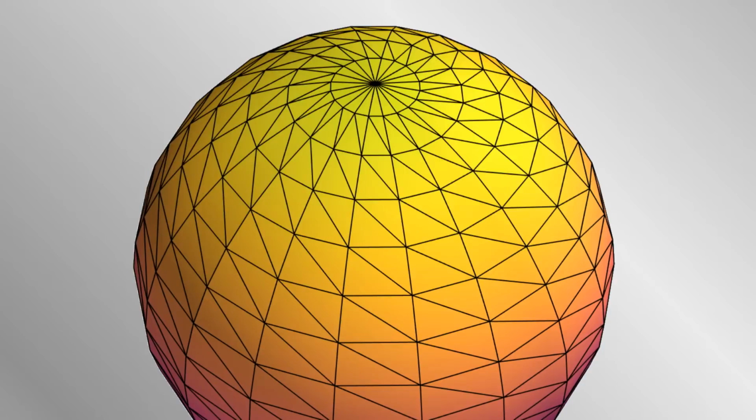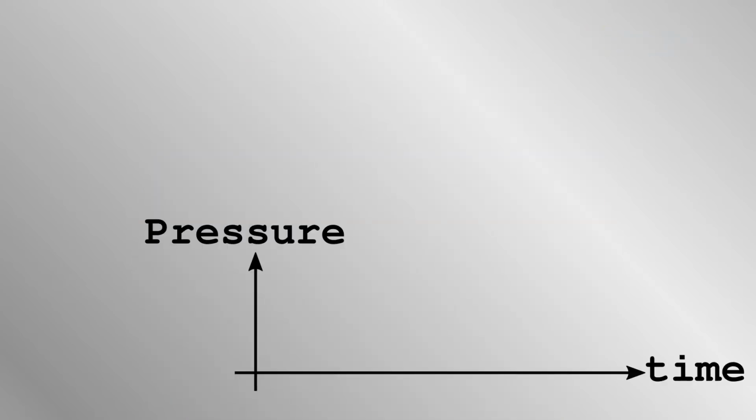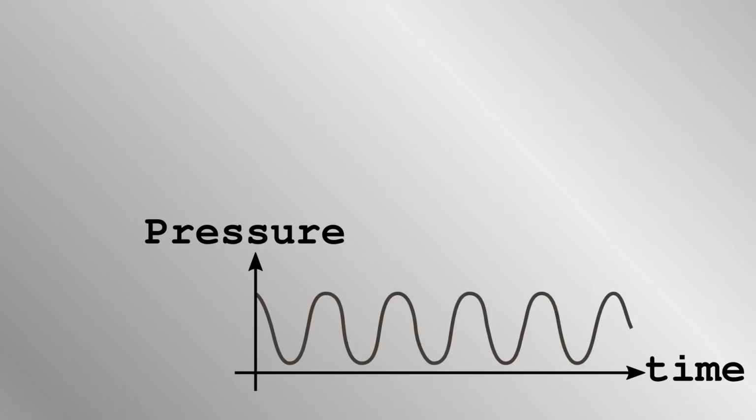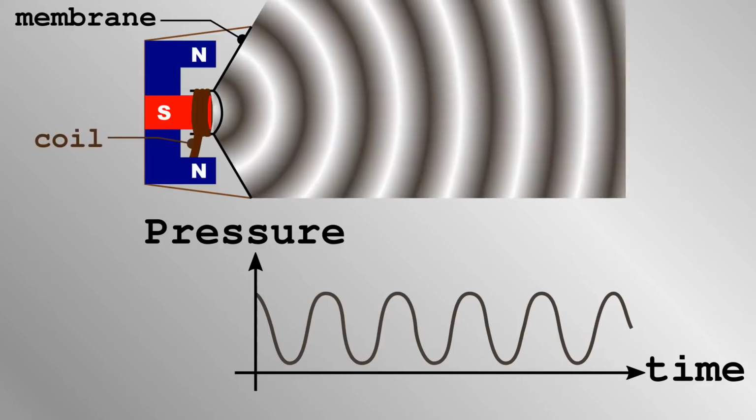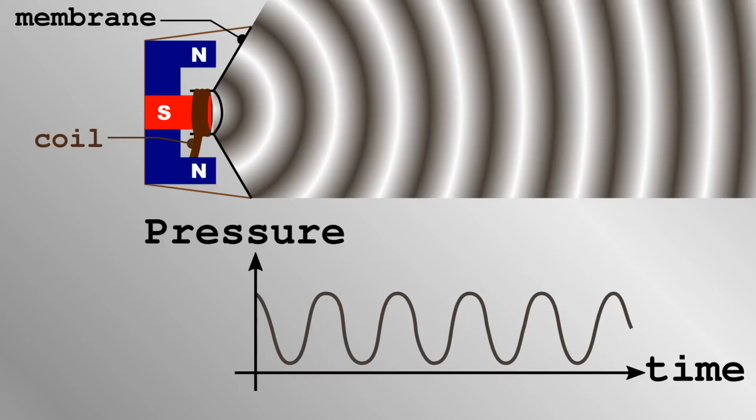No matter how complicated, it all comes down to addition, multiplication and jump instructions compiled into functions. Sound is the other major form of output from a computer. Sounds are waves of high and low pressure moving through the air. Speakers and headphones produce sounds by moving a membrane back and forth. There is a permanent magnet attached to the membrane inside a fixed conducting coil. An oscillating current through the coil pulls the magnet in and out, making the membrane oscillate and creating a sound.